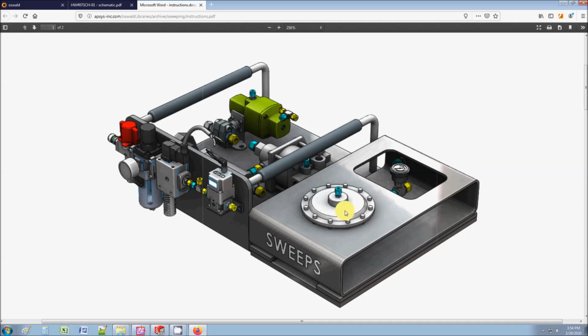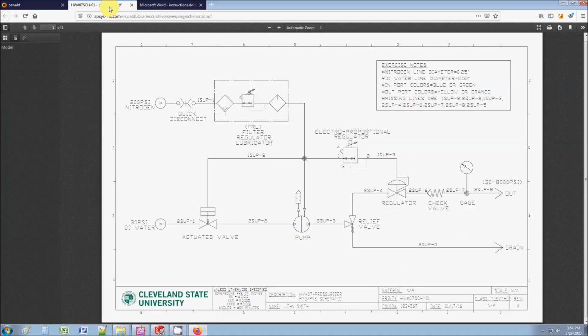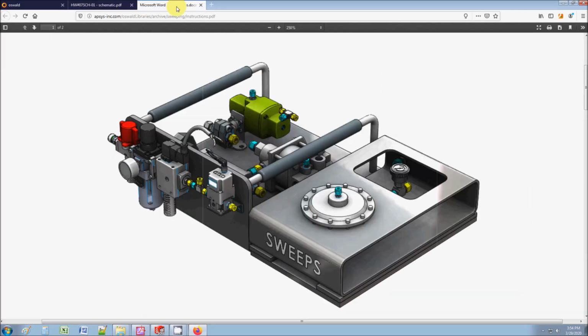Here's a pump, and it's kind of interesting. This pump can deliver 10,000 psi. It's right here. Yet you're feeding it just 45 psi of air. So the reason it can deliver 10,000 psi of water from just 45 psi of air is because of this mechanical advantage that happens inside the pump. And it's just kind of interesting how that works. So you feed it here, there's the air, and then the outbound is on this yellow fitting that is displayed there.